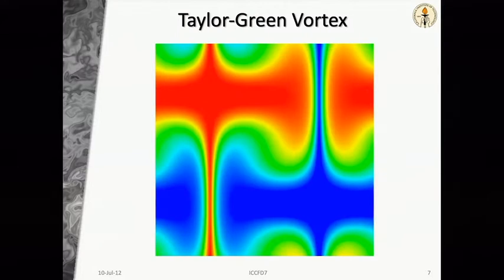Physically, when you put a thin strand of air and fuel next to each other, there's a very sharp gradient, so things will want to diffuse out very quickly. If you leave this running for long enough, eventually everything will be green. The whole concentration field will be uniform. But without diffusion, if you don't implement any diffusion, what should happen?